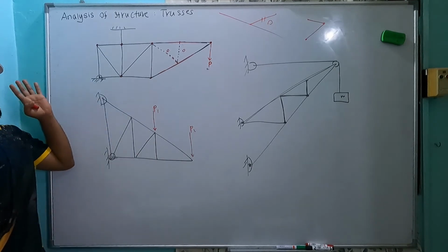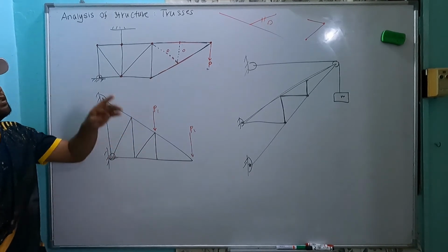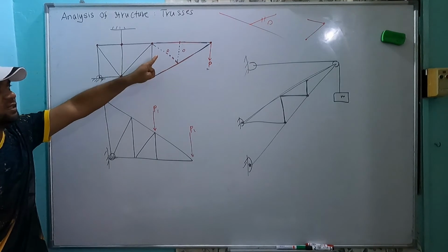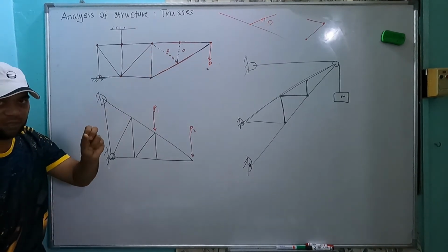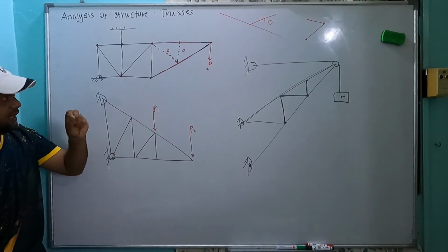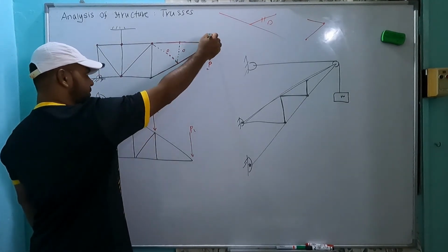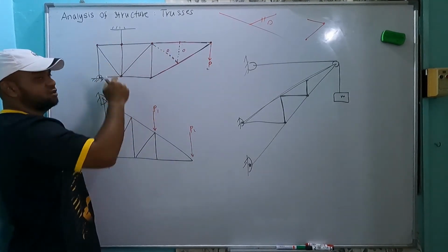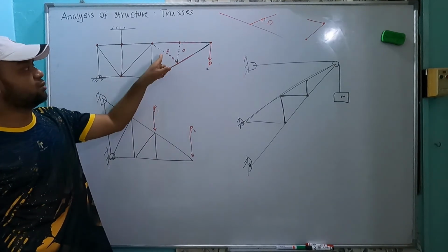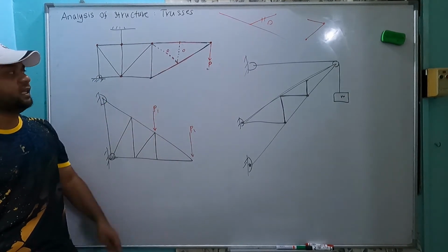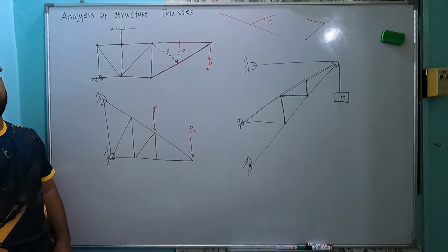Even if you calculate from your analysis, you will find that the force inside these two is equal to 0, meaning that the load will not go to that component, it will go directly to this one, and this one transfers to the joint. In this case, these two components have no function to exert any forces.